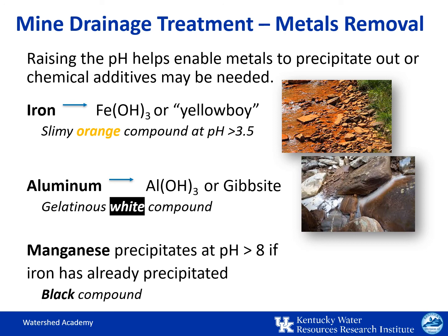Like with pH neutralization, the method should be selected carefully based on the metals that need to be removed and their concentrations, its effectiveness, availability and cost, and byproducts of the reaction. Iron and manganese are common in groundwater and may need to be removed from solution with the addition of potassium permanganate. Potassium permanganate oxidizes iron and manganese into their insoluble states. Once these metals form solid precipitates, they can be removed by settling ponds or basins.